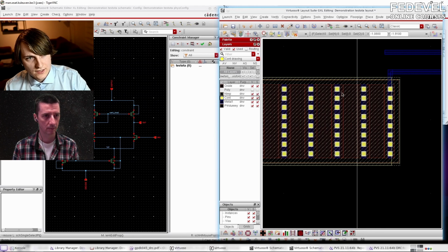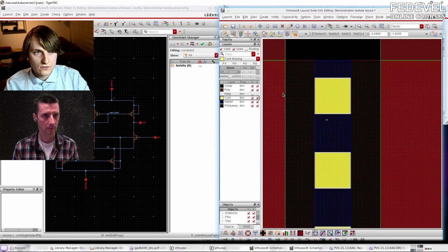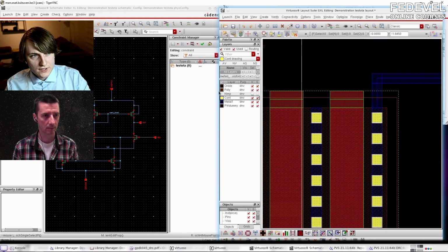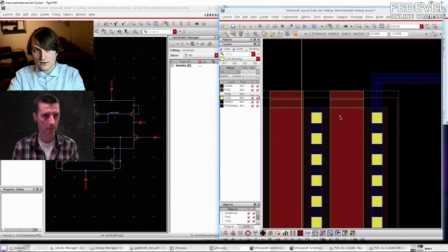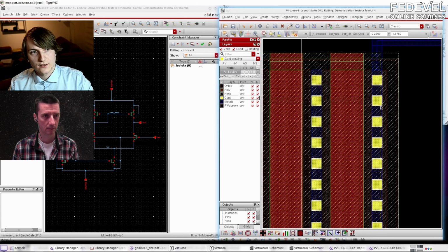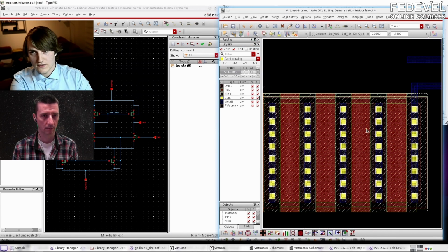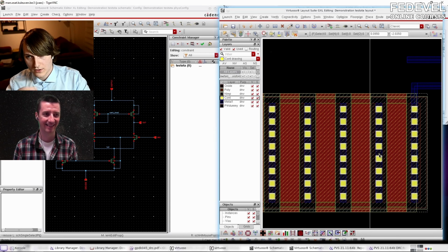a different technology to indicate, look here, these contacts, you have to actually make a hole through the oxide to connect to what's underneath. We then place poly here on top to make the conductor of the gate. So this is the terminal we connect our gate to. It's polysilicon, so it's a conductor. And then underneath, we say it's N implanted. So they shoot N material at this, but in this case, they do it after they've already made the gate. So the gate blocks the N from getting underneath the gate and it only gets in the slots between. So this is what they call a self-aligned transistor.